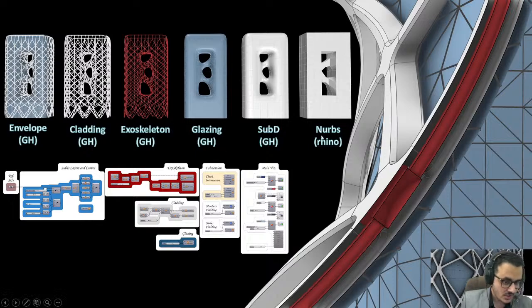As you can see here, at first I did the NURBS, because when I started to work on this design, it was the early stages of SubD in Rhino, so there weren't a lot of tutorials available. So I did this one with polysurfaces, and after that I turned them into SubD with Grasshopper, and after that I worked through all of these processes to get the final envelope. I've done the glazing, the exoskeleton, the cladding.